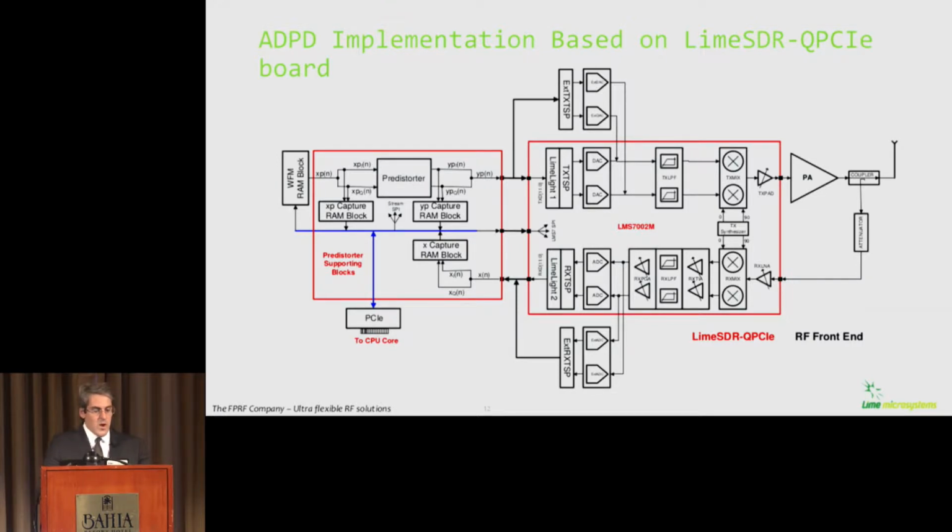Waveforms at the input and output of the predistorter, as well as from the output of the PA, the power amplifier, are captured, and those waveforms are brought together to the CPU core, to dedicated software which is used for calculation, and it exactly finds new coefficients and over the PCI Express interface loads them into the predistorter model. So in every adaptation step, the predistorter obtains new coefficients.